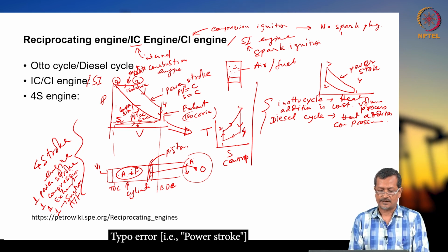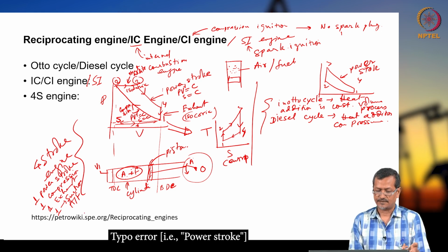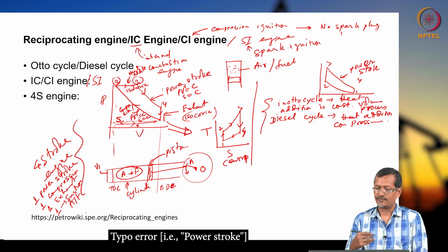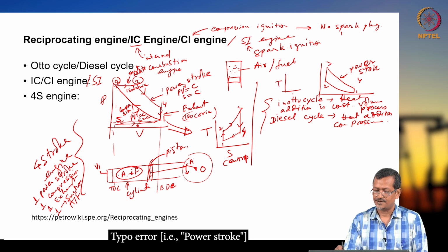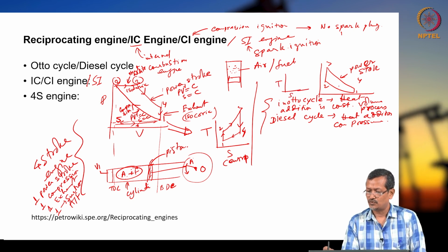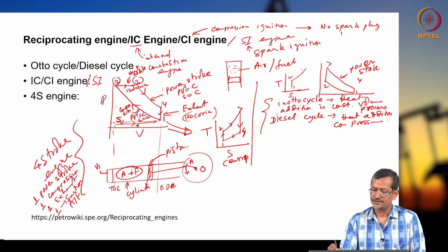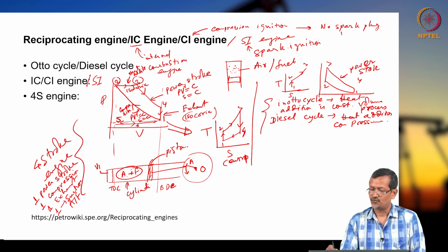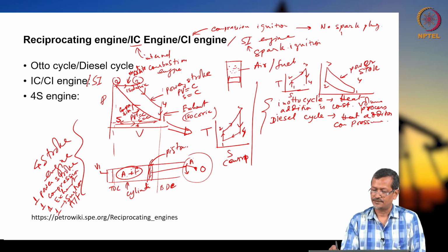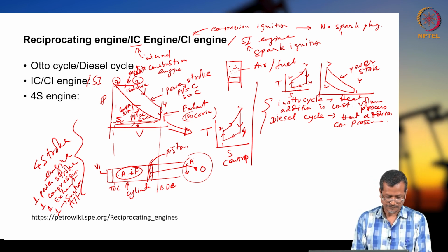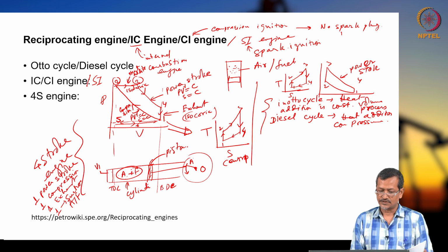Okay. So, in the exam I can ask you to draw the TS diagram from the PV diagram, or if the TS diagram is given, can you draw the PV diagram? Okay. If I draw the TS diagram for the Otto cycle, 1 to 2 is an isentropic process, 2 to 3 heat addition, temperature increasing, 3 to 4 again constant entropy, 4 to 1. So, both curves are almost similar. Okay. So, all these are 4-stroke cycles. Now, I will go to the 2-stroke cycle.